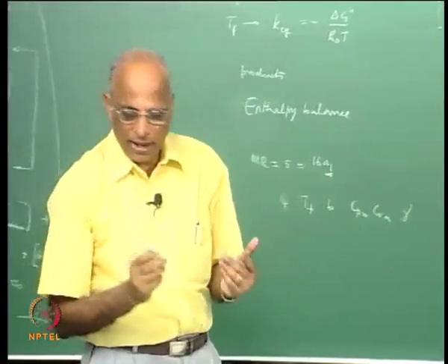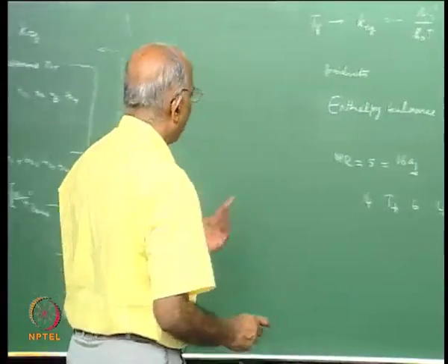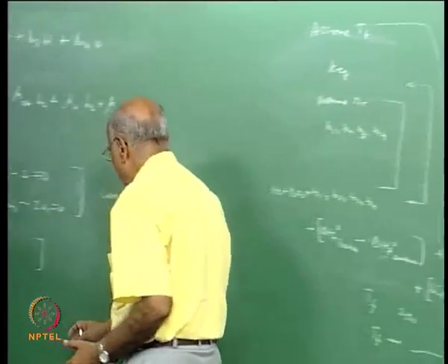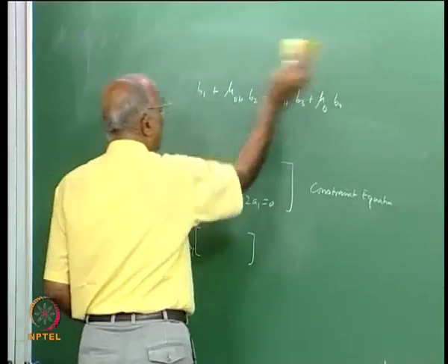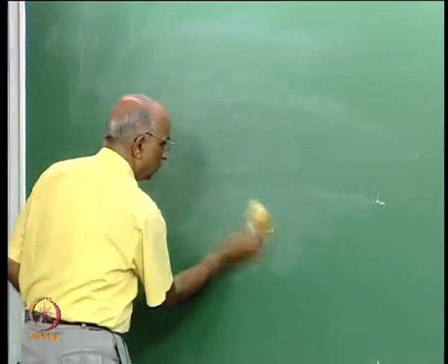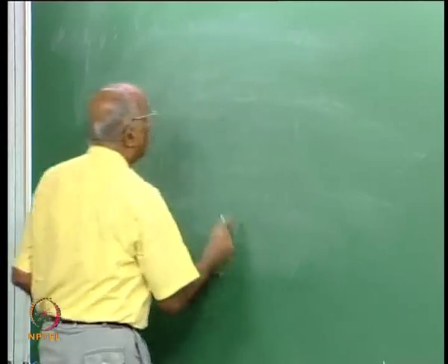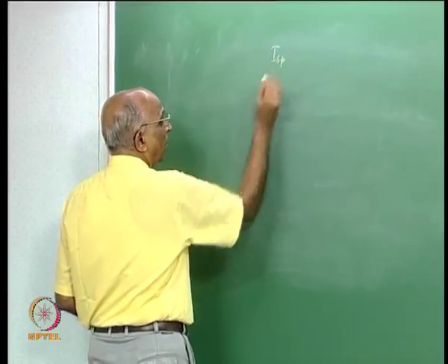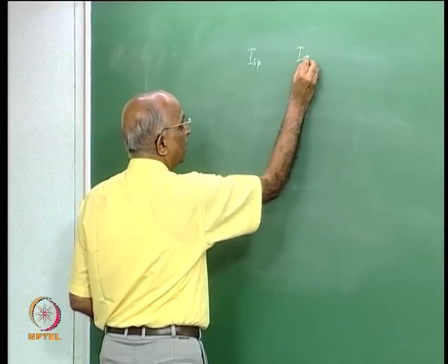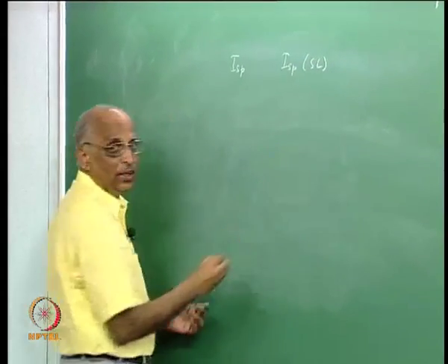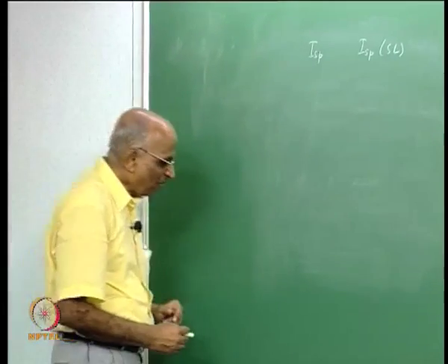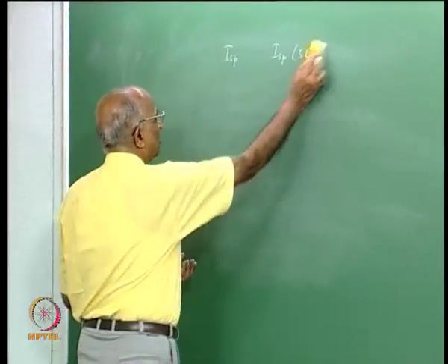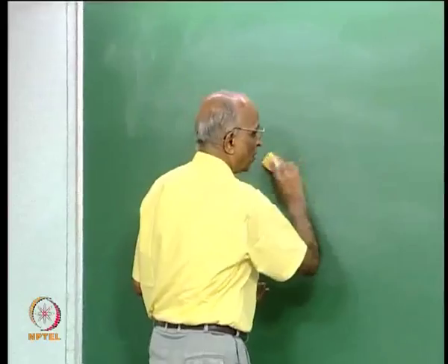I think this is all I have about the slides, and now let us go back and try to understand the last part of why we do all this equilibrium analysis. Are there certain things which we need to understand further? One thing I want to qualify is that when I put the ISP in that particular plot, it is ISP at sea level, because we found ISP will change. At sea level the ambient pressure is 1 atmosphere. Now let us consider the last part of the dissociation before we can look at the chemical propellants for their characteristics.